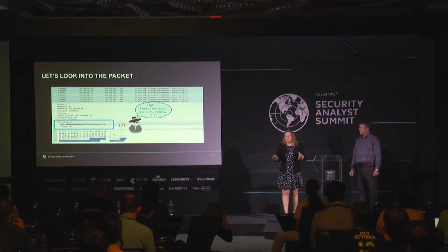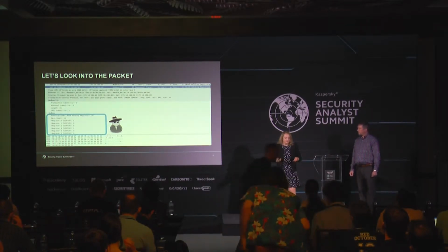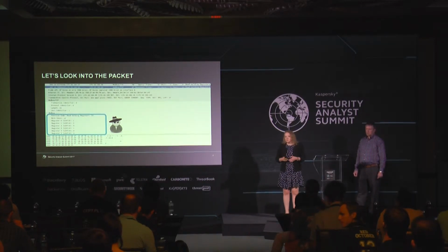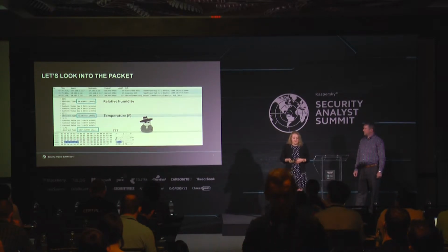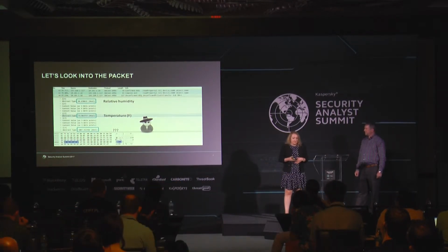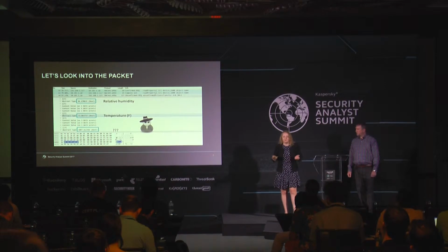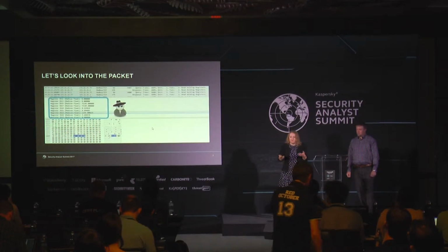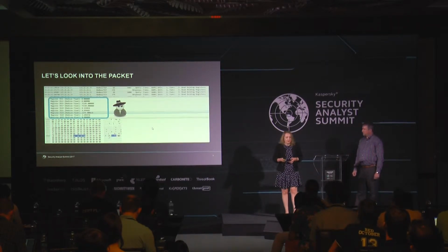But there are a lot of open protocols in industrial. So let's see what the attacker will see there. Modbus: 1 and 0, probably on-off states, but could be any status data. We don't know. BACnet: you see some numbers. Some we can guess because it's BACnet; something can be humidity, temperature. But then at the bottom we have 1087, what on earth could be that big? This is a floating point, and the value ranges from 3 to 71,000. I have no idea what it could be.